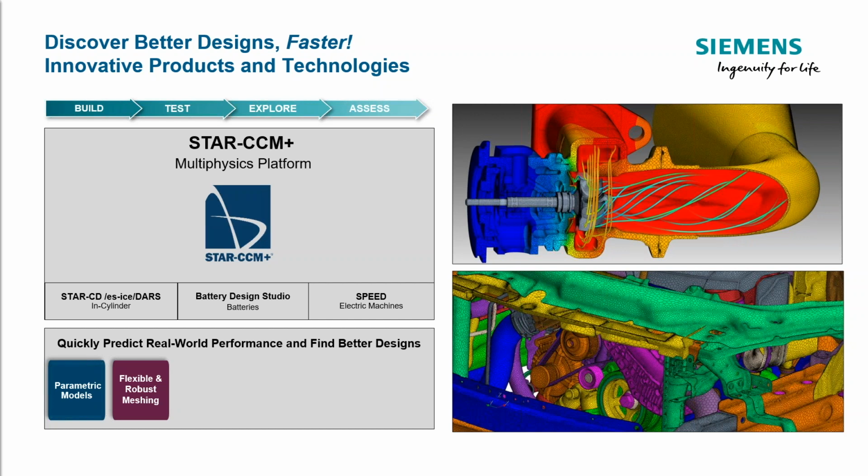In addition to the polyhedral meshing capabilities, it has a surface wrapper too. The surface wrapper enables you to bring in nearly any geometry that you have, no matter how complex it is. The example that they have in their demo setup is bringing in a motorcycle that has all the little features of the handbrakes, items like that. You can apply a surface wrapper to that instead of trying to clean up that geometry, and use the surface wrapper to create another mesh above it and use that as your basis for your volume mesh. It really optimizes and streamlines the workflow and allows you to reduce time up front.